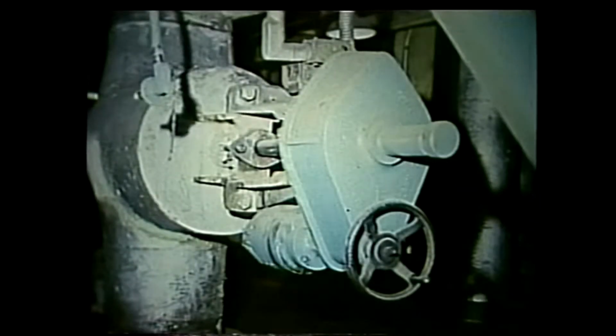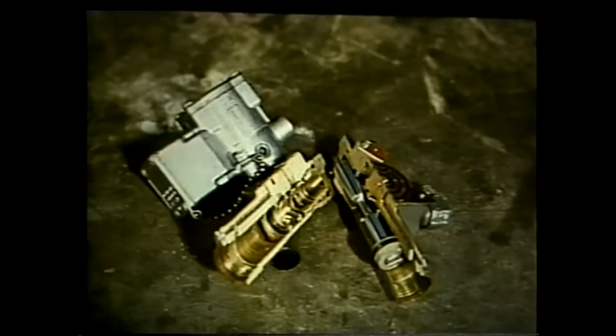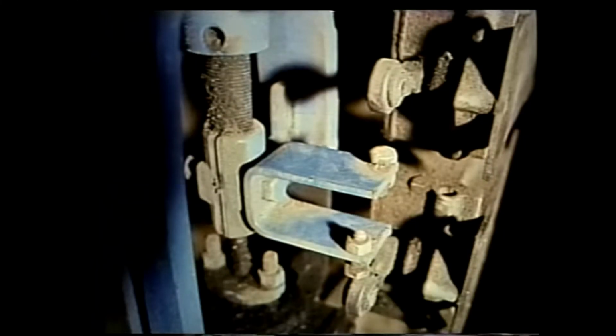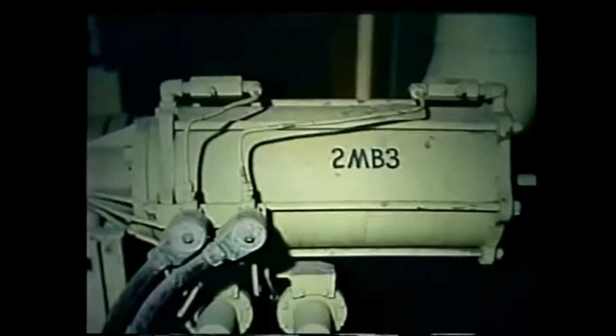Motor-driven operators are often used in place of the hand wheel. Electric, hydraulic, or pneumatic motors provide ease in handling, and they allow remote control operation. Electric solenoids are usually used for remote operation on short stroke applications, usually a quarter of a turn or less. Electric motors are connected to the valve stem. They're usually run at low speed, but are high powered. When the motor is energized, the stem starts to rotate. A limit switch stops the motor when the valve is fully open or closed.